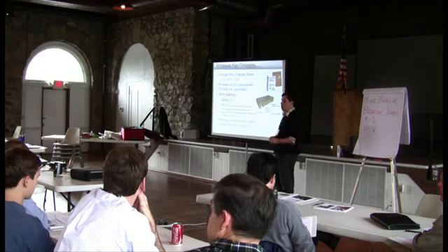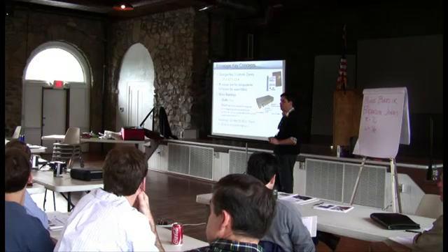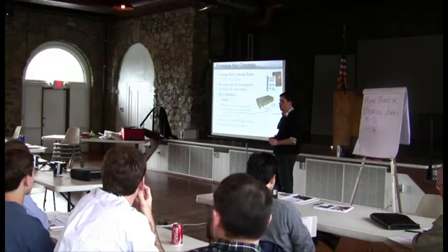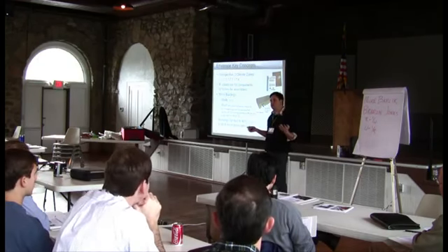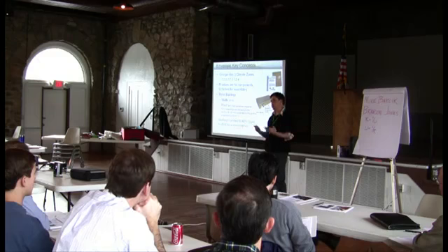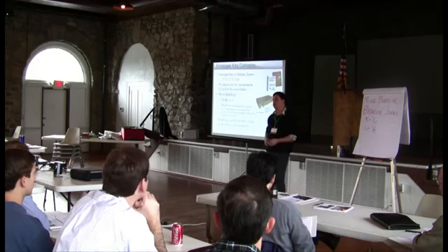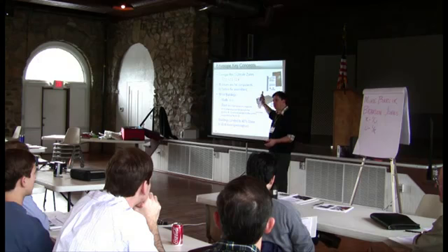3 inches of fiberglass? That's not going to get it. Well, that's been what the minimum has been for years. It was 2 inches. It's 10 foot here. Glad we're having this discussion. It depends on whether or not it's conditioned. If the space is not conditioned, it's not an issue. If it is conditioned or semi-conditioned, that's where the code will kick in.